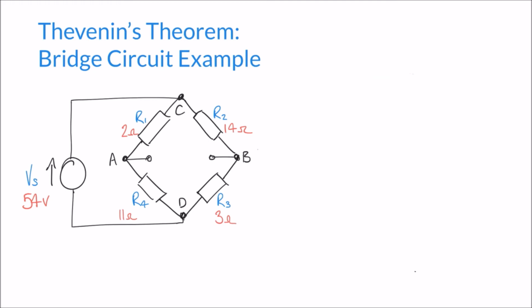Let's begin, as we say, by getting rid of our voltage supply there and replacing it with a short in this case. So I'll just represent that by this red connection there. So we've short-circuited our supply from the circuit, and the objective is to find the resistance from point A to point B. Now hopefully it'll be a bit easier to visualize once we've redrawn this circuit, but let's start at